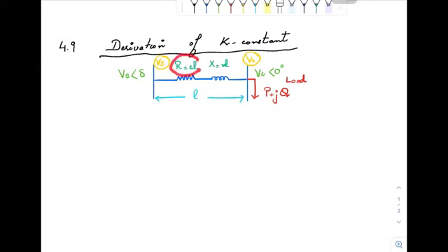This is the resistance of the feeder and this is the reactance of the feeder. So the overall resistance is equal to the product of the resistance, that is in ohms per mile per phase, into length. So this is the reactance in ohms per mile, and when multiplied by length it will give the overall reactance in ohms.